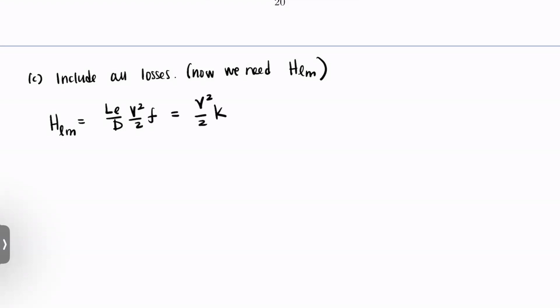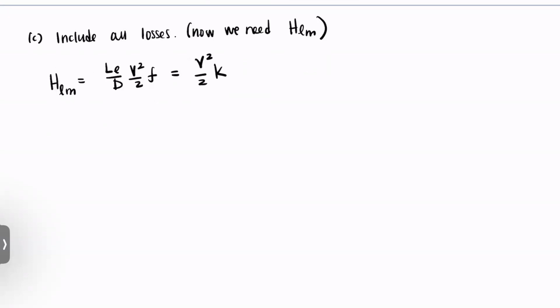And so what I like to do for problems like this is just make a table. I have my fittings, the different types of fittings in my system, and then I write down the quantity that I have and what the K value is. It helps me stay organized.